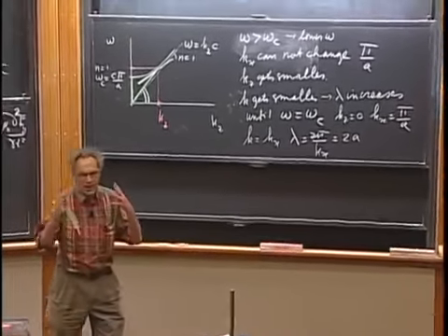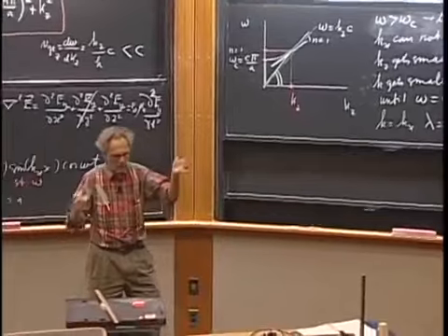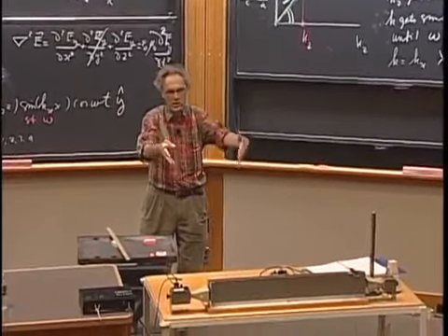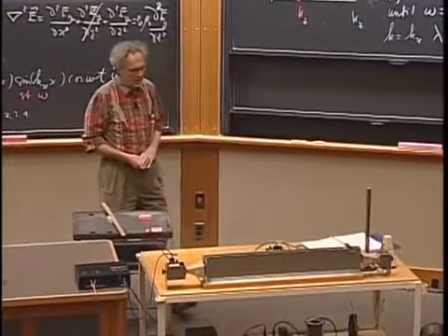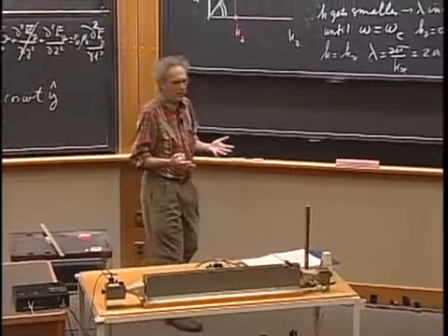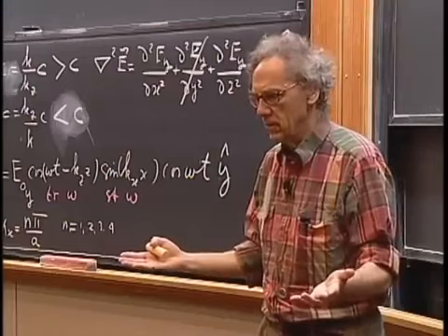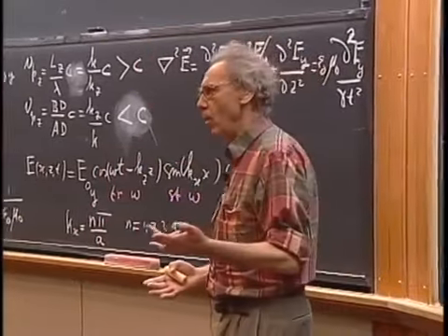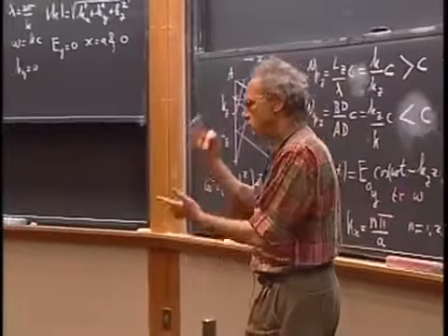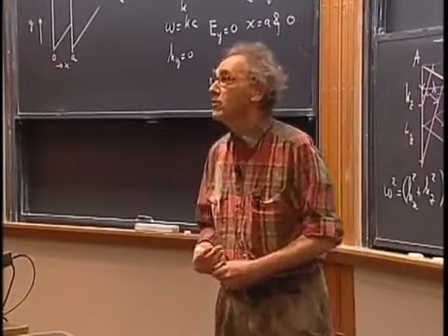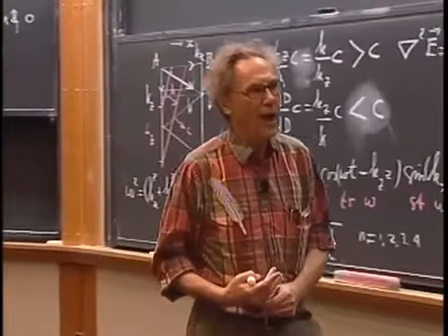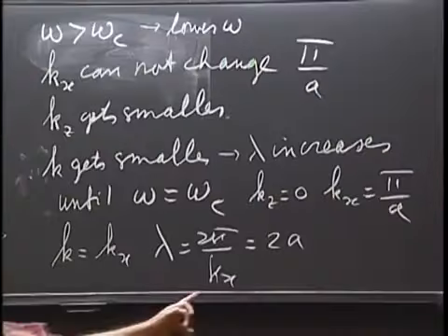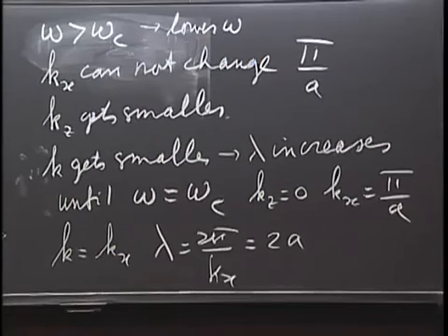It means if I have a given frequency, which we do have here, which I cannot change, I have 10 gigahertz. And 10 gigahertz has a wavelength of 3 centimeters in vacuum. It means the moment that I make a any smaller than 1.5 centimeters, there is no propagation anymore in that direction. Because now I can no longer meet the boundary conditions for kx, and I will demonstrate that as I did before. This is not the first time that you will see that.